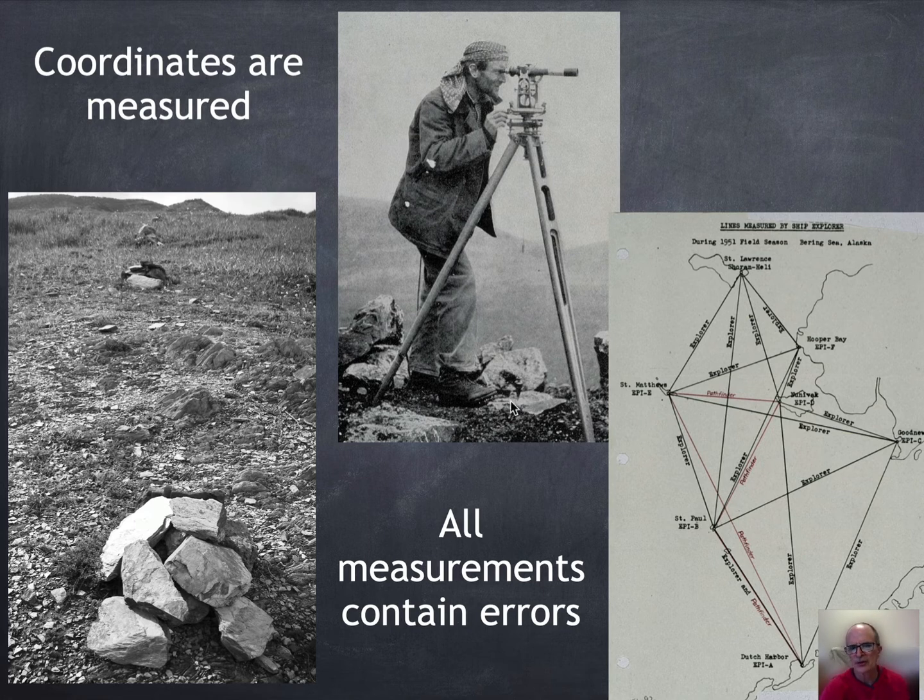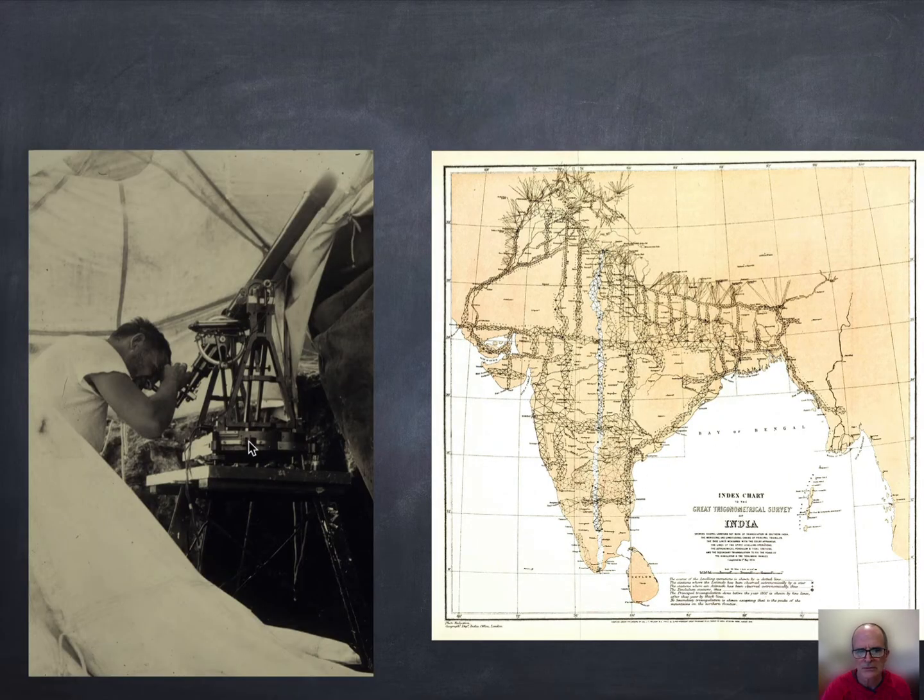There was some optical interference and refraction, so that changed the optics slightly. I wrote something down wrong. It was a cold or a warm day, and so the cable that we used to measure distance expanded or contracted. Taken together, these errors get quite large over large networks. We have to basically pull those errors out.